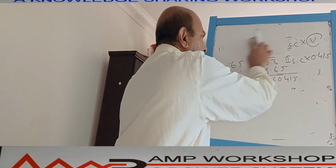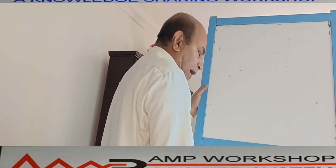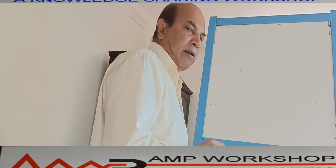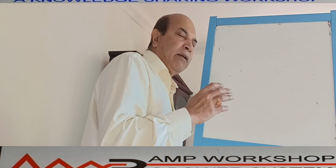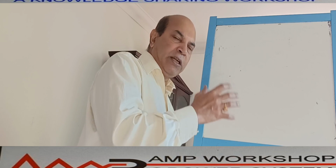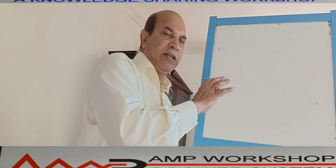Okay, so this is how I have calculated for a simple network, but for any network, if you want to do it by hand method, you have to calculate in this way. The simple way is, first you have to draw the circuit diagram. From the circuit diagram, for every equipment you have to calculate the per unit impedance. Per unit impedance for the utility is very simple: base MVA divided by utility MVA.